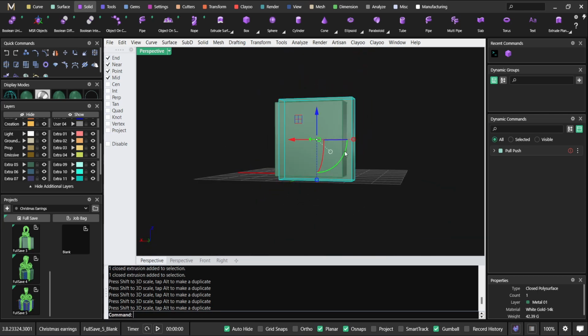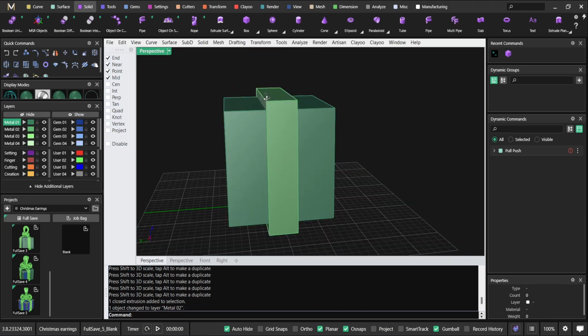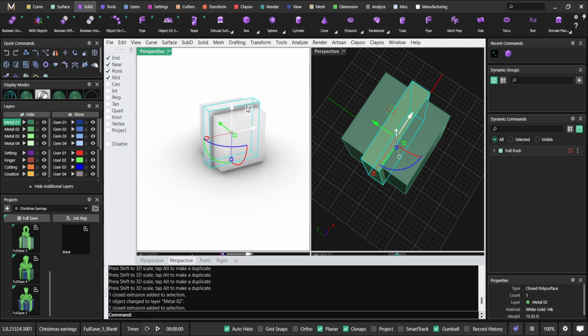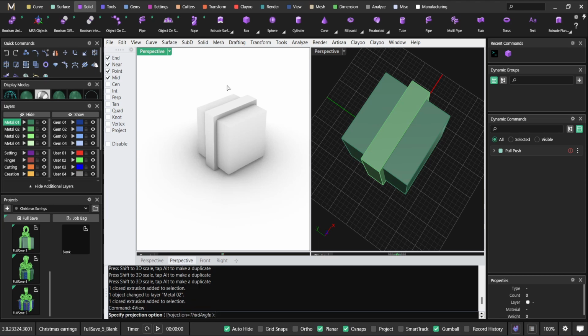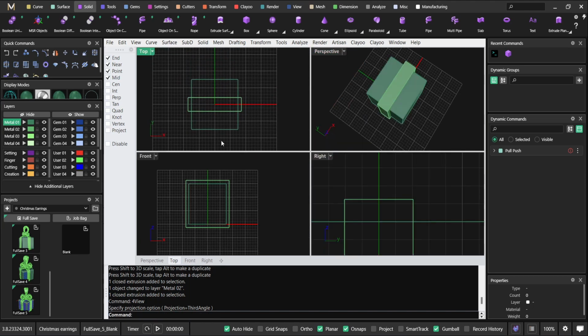Okay. You can put it in another layer if you want to. Okay, so I got this. Then I'm gonna use not this view. As you can see now, I got 2 perspective viewport by default. I want to change that. I want to make sure I have 4 views, 4 regular views. So you can just type in on the command line 4 view, enter. Just do it twice. So that's gonna reset your viewport, just like this.